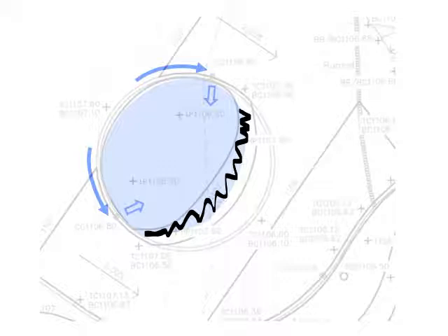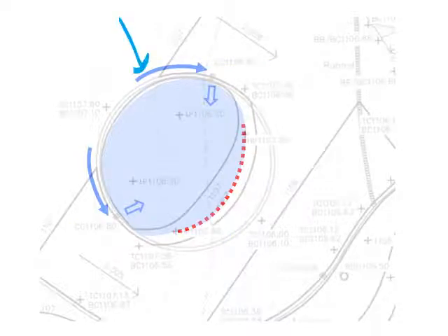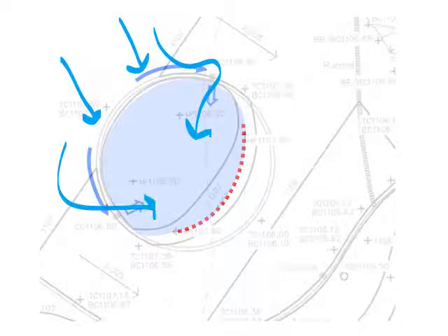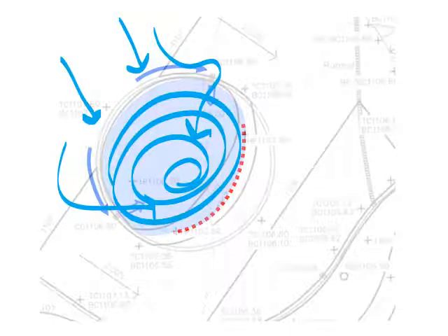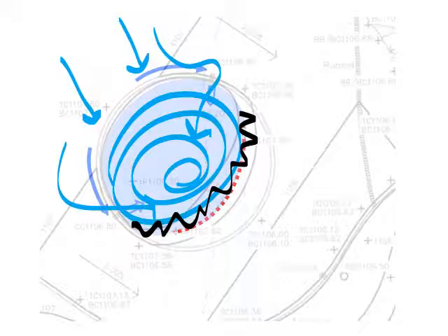And you're creating that berm by having your high points clearly shown, and these high points have to be well above your curb cut elevation. In fact, you would like them to be half a foot, if possible, above your curb cut elevation. So again, water flows down, it flows into the system, it starts to fill up the system because you've created a berm down here that keeps it from overflowing downhill.